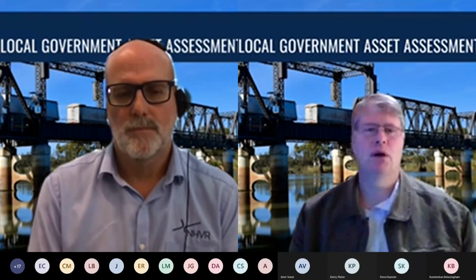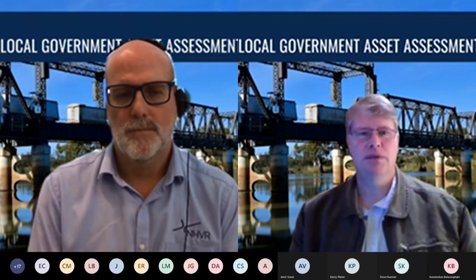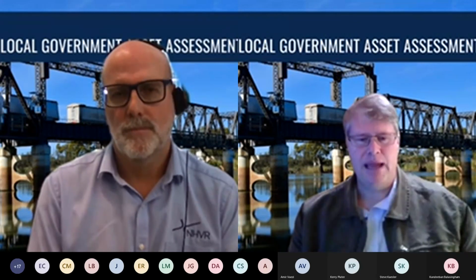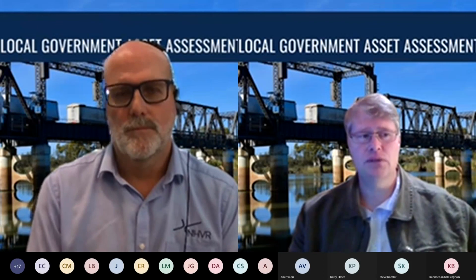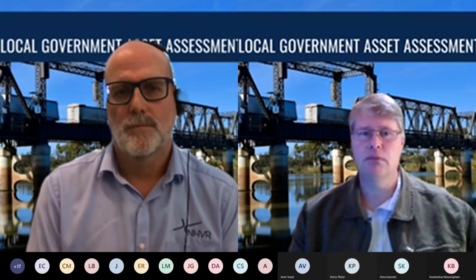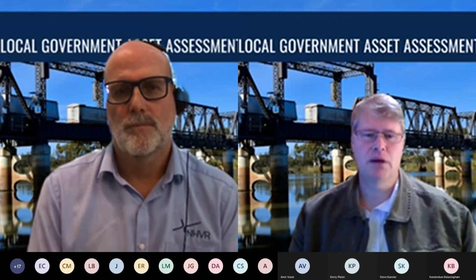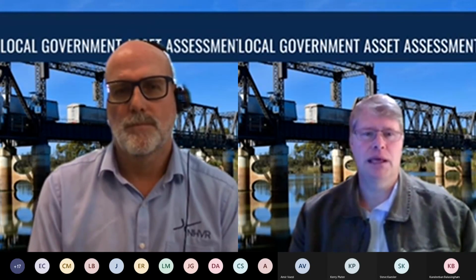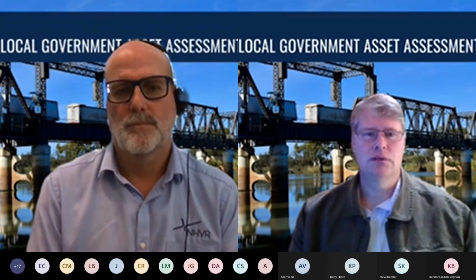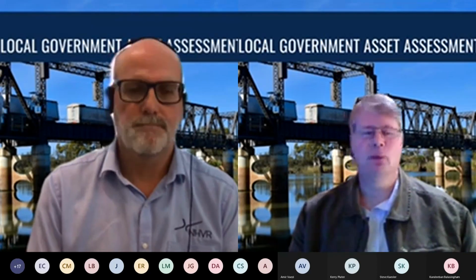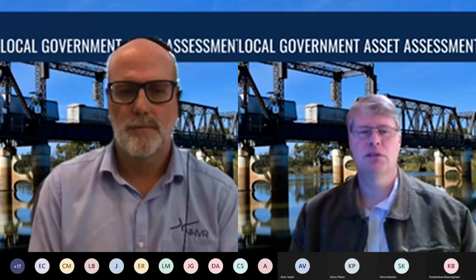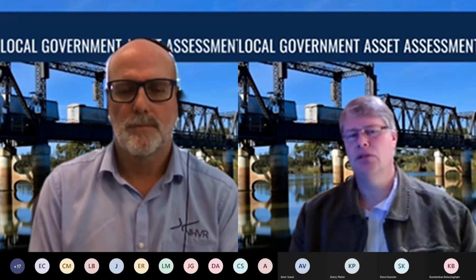That's why we've always got to keep an eye on condition. If we do end up with degradation in condition, how much is that affecting previous access decisions that we have made? You can get to a situation where you start thinking, oh geez, now we're in a position where maybe those assessments, if we did them again now, we wouldn't provide access. Well, we need to do something about the condition of the structure in that situation, or move to limit access, provide alternatives, that sort of thing. That's why it's so important to be doing regular Level 2 inspections and incorporating that into your decision-making process around access.